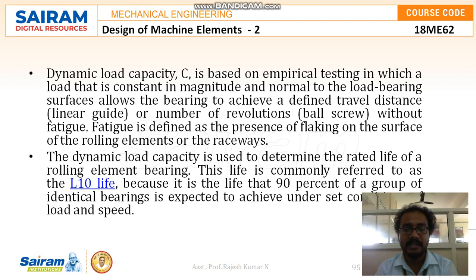The dynamic load capacity is used to determine the rated life of a rolling element bearing, and this life is commonly referred to as the L10 life, because it is the life that 90% of a group of identical bearings is expected to achieve under set conditions of load and speed.